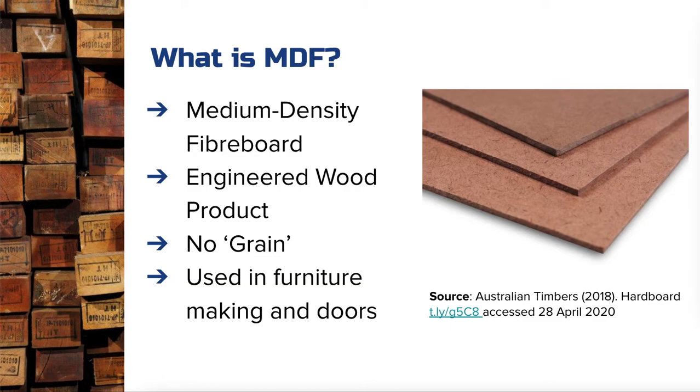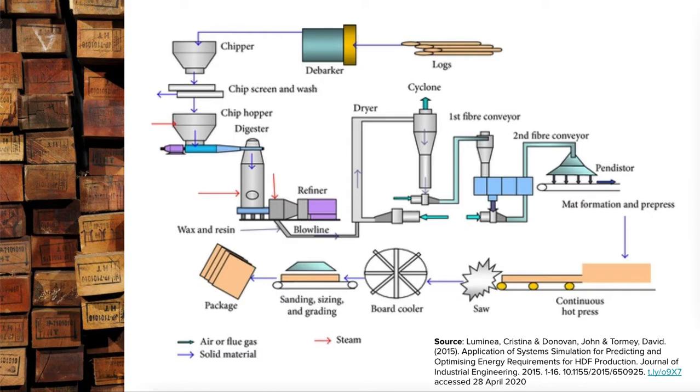It doesn't need to look like fiberboard because you can apply a veneer to it. You could paint it, of course, but you can apply a veneer to it. So you could apply a solid veneer over the surface to make it look like a solid board, but have all the benefits of the strength and the cost effectiveness of MDF. Just like they do for kitchen cabinets, you could even vacuum form some thicker polyurethane coatings and things like that over them. So you're not just limited to the raw MDF look. It's definitely something that can be enhanced, but you get the benefits of the MDF on the inside.